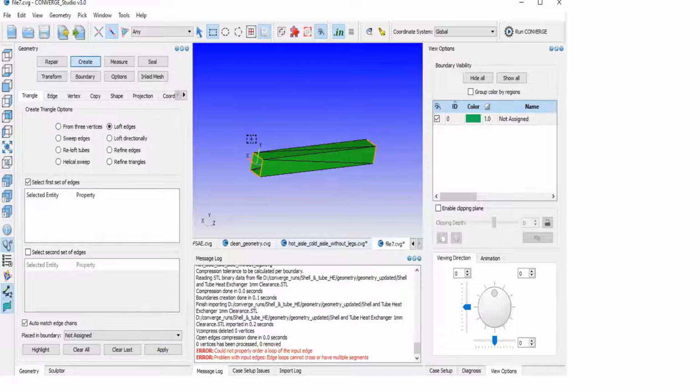If you can see, what I did is I lofted the edges. I created an open loop, and then there is an option to loft the edge. But you can see there is an open edge here. So I'll now patch it, which I did earlier.